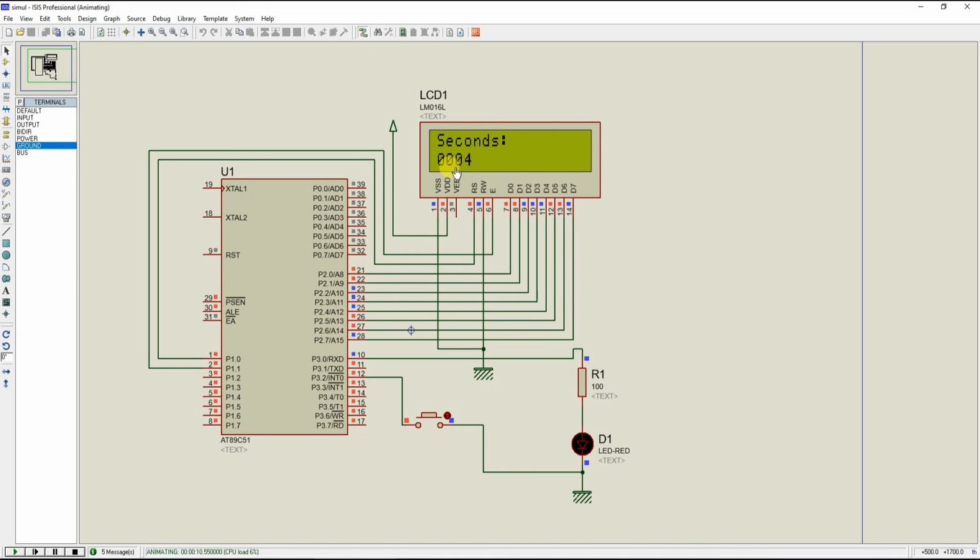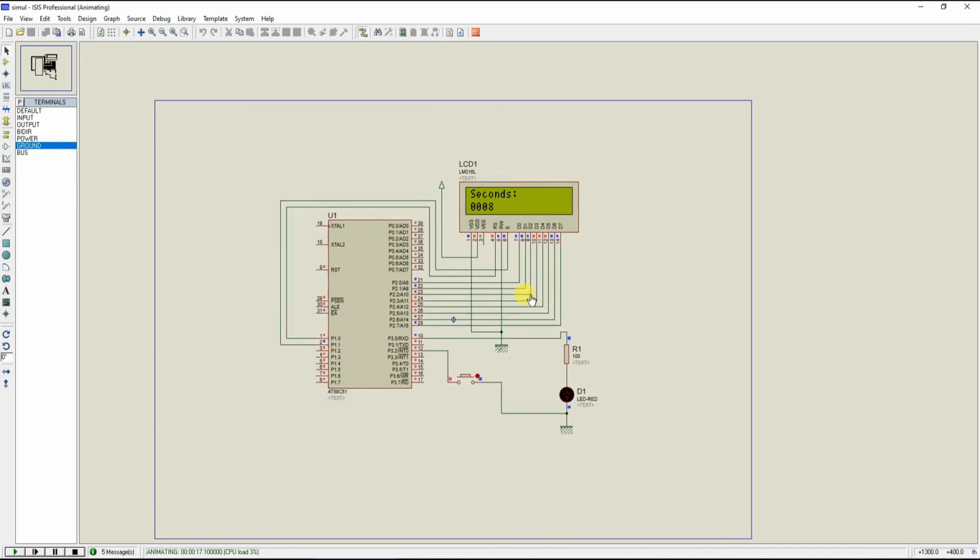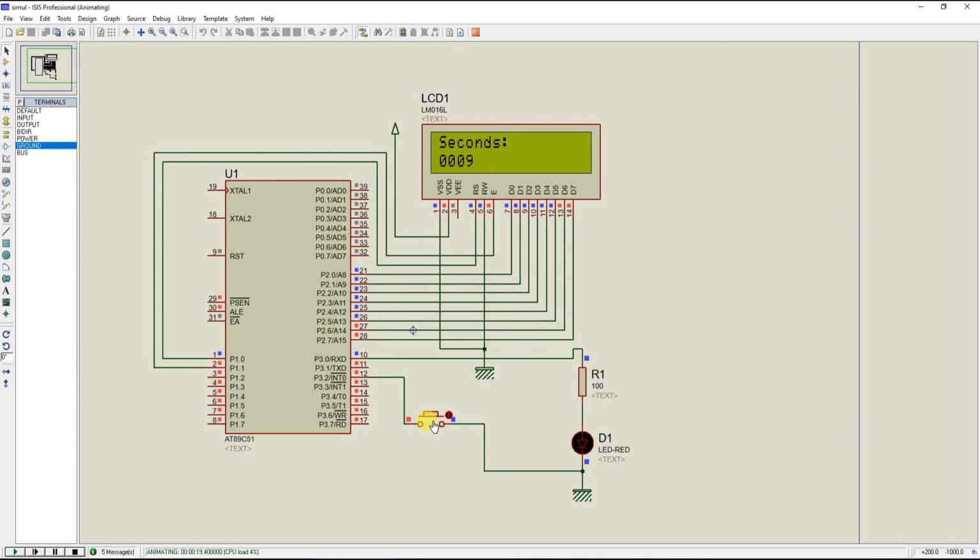Now what I want to do in between this execution is I want to stop my microcontroller, or interrupt my microcontroller. You can also see my LED status is off. Now you'll see if I just press this button once, what happened? My LED immediately turned on. But do you see any change here in the execution? There is no change, because when the interrupt occurred, the program immediately went to that location, executed that pin toggle function and returned back. And it happens so fast at 11.0592 megahertz, or whatever crystal frequency you are using, that you will not even observe that there was such a change happening.